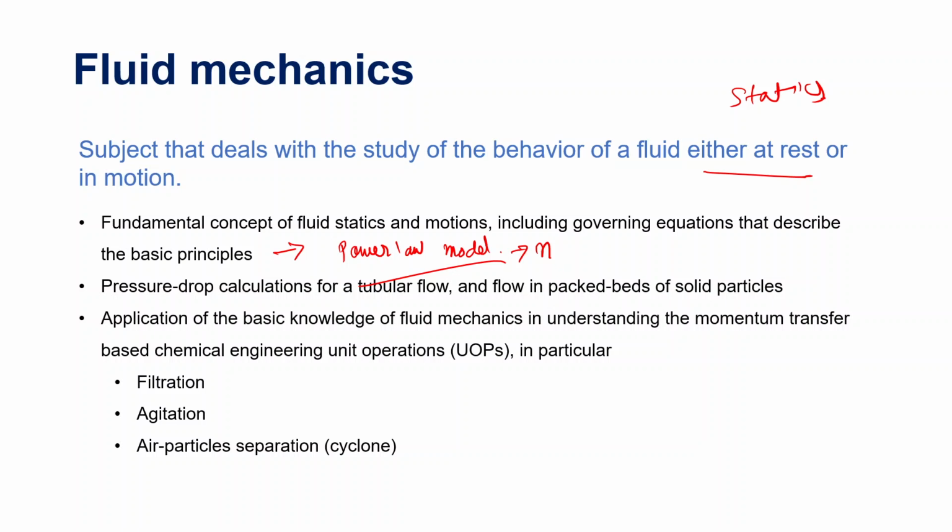While solving the questions, we saw that questions related to commenting on the rheological behavior of the fluid are very frequent. Using the power law model, we can find the viscosity of the fluid. That question was also very common. Then we looked at the pressure drop calculations for tubular flow, where we used the equation of continuity and Bernoulli theorem.